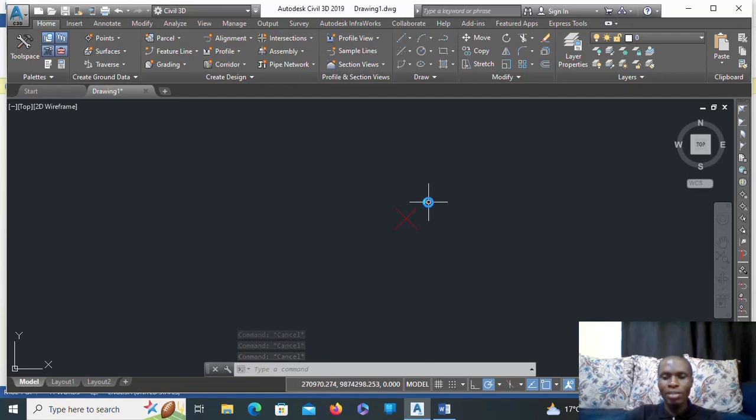Something else about Civil 3D is that if you want to highlight a point that has a polyline, and you highlight from right to left, it doesn't matter whether you capture the whole object or not. So long as you have captured a smaller section of the object, then the whole object will be highlighted. This is different from highlighting an object from left to right.